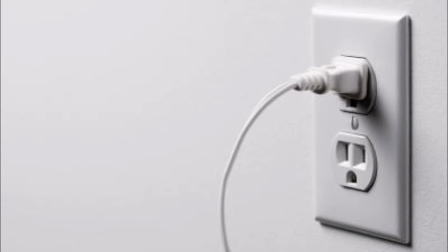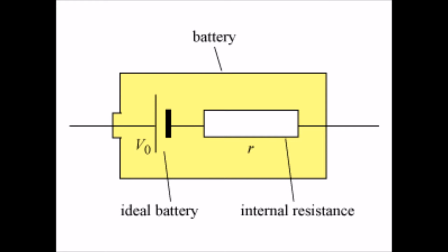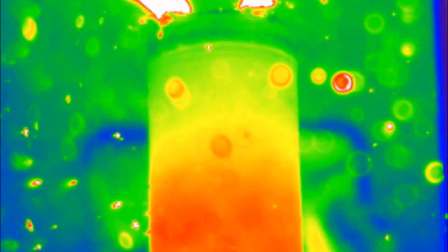The amount of charge your cell phone and laptop batteries can hold decreases after a few years. Lithium-ion batteries develop increased internal resistance over time, which decreases their ability to deliver current. In addition, lithium-ion batteries are vulnerable to a number of potential problems. These include overheating at the anode and oxygen production due to overheating at the cathode. These two problems together can cause a fire.